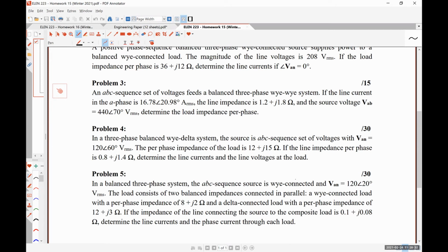It'd be wildly different if we just said, screw it, everything's between the A and B terminals, because then you'd have a huge load there and no load between B and C or C and A. So it's just simple little practices like that that are kind of common sense. You just specify building 2 is supposed to be hooked up between these terminals, and building 3 between these other terminals, so that you rotate it around the phases to balance things as best you can.